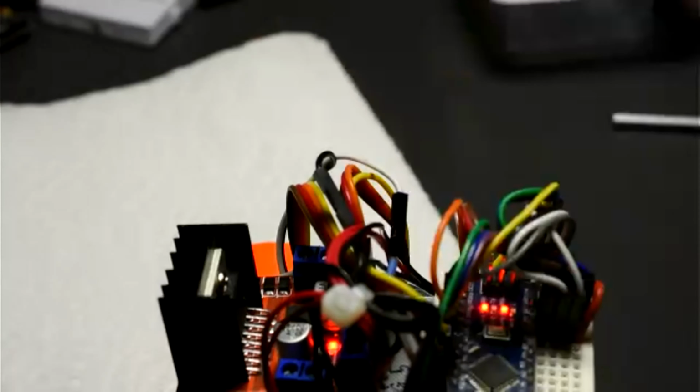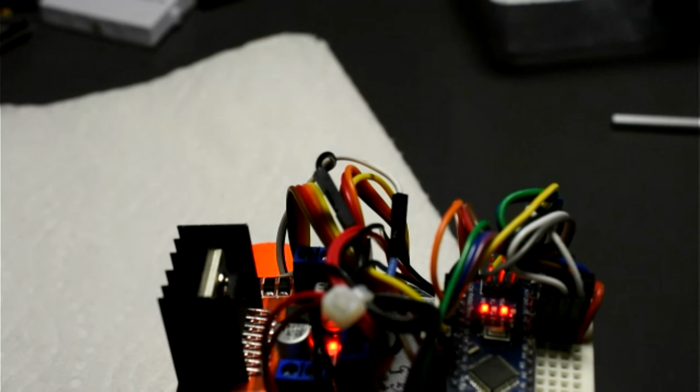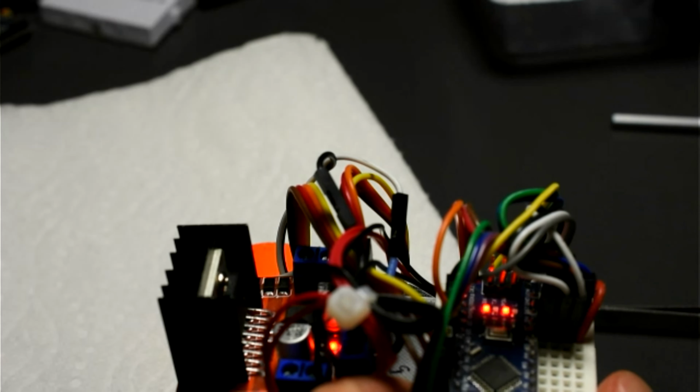I have that switched where I have 6 and 10 for one motor and 9 and 11 for the other motor. And as you can see, analog write, if 2 of the pins match the other 2 pins, then no motor will spin. So obviously I've hooked it up in such a way where one of the motors is receiving digital write 0 and 0, and the other one's receiving 255 and 255. So all I have to do is switch 2 pins.